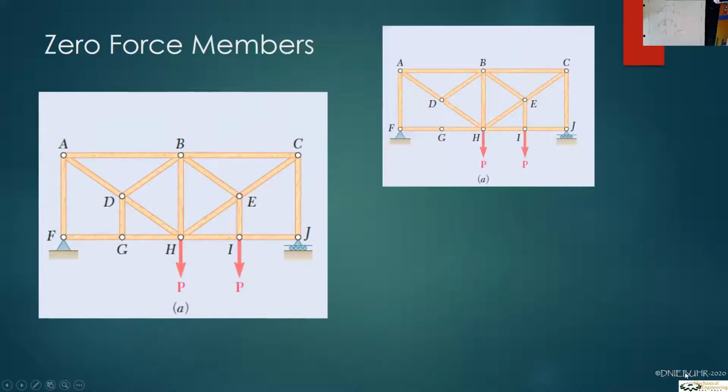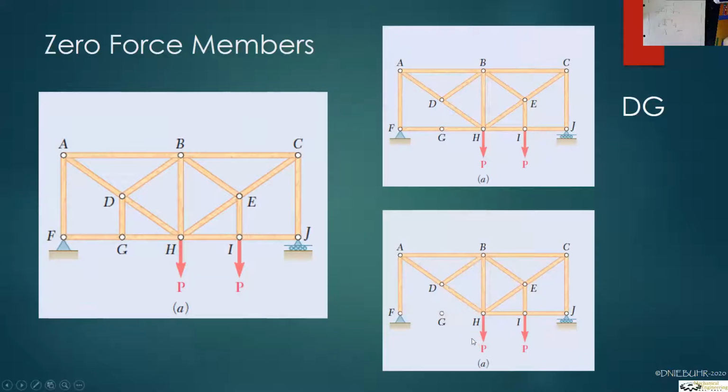So first thing we have is, I'm going to say, DG. I did this a little differently than the other one, but here's DG. That disappeared because that was the most obvious one. But notice how once it drops out, because there's no FX, that means FG has to drop out, which also means that GH has to drop out. Here we get that. And I left the G kind of floating there because you wouldn't physically remove the member. This is just for illustrative purposes.